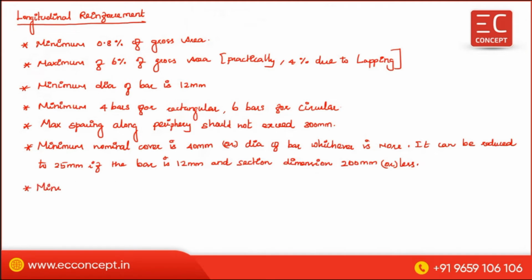Next one is minimum 0.15 percentage of gross area for pedestal.